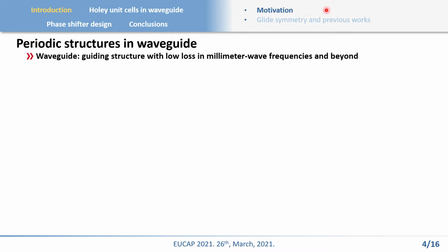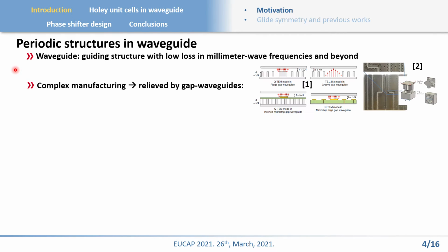Waveguide technology is one of the preferred guiding structures for electromagnetic waves in higher frequency due to its inherent low losses regarding traditional technology such as microstrip. Therefore, there is a need to use this technology in the design of the devices at millimeter wave frequency. In addition, the manufacturing of the waveguide is relieved by gap waveguide technology that allows the cost-effective fabrication of the